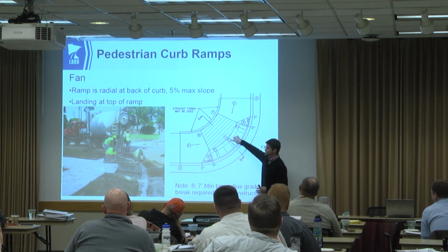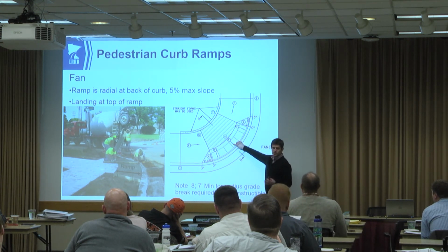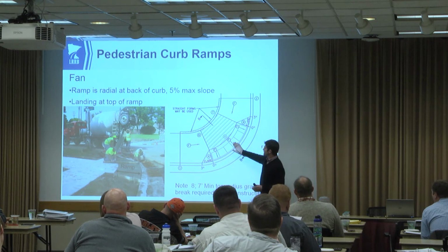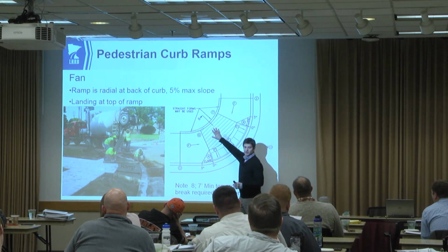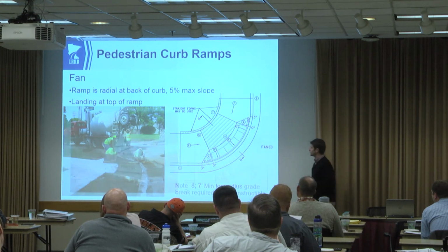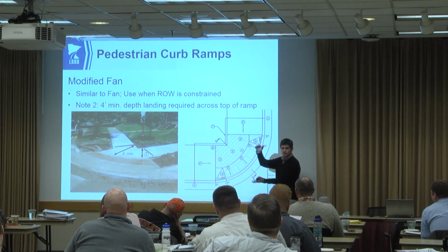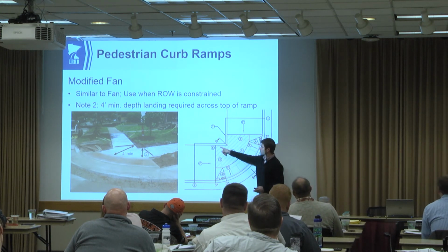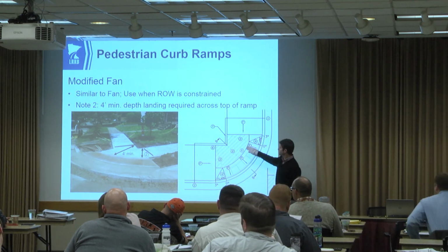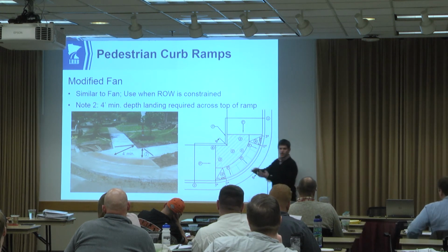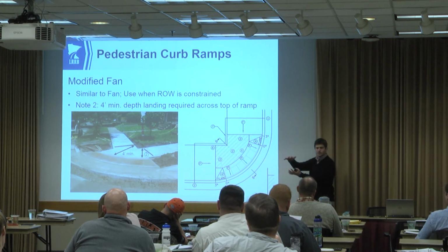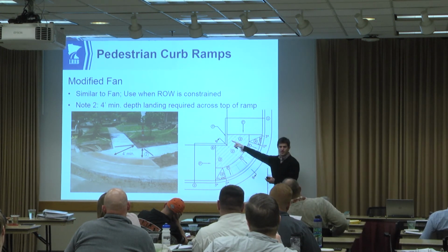See, we've got these Fs for flat slope. If you need to, they can be S slopes. You've got a landing here, it's just preferred to have it be flat. So then you make up part of your elevation gain to here. If you've got a right-of-way problem, as Ann mentioned, or maybe it's even a building right there, or you've got a higher elevation difference to make up, you can use this V-curb off the back. So you can kind of ramp up, landing, and then you have a V-curb. Helps you achieve a greater elevation difference from flow line to where you're tying in at the back.